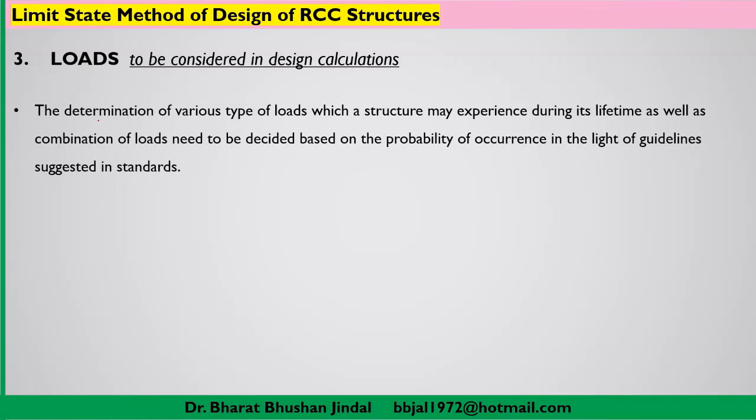Now, what are the loads which we are going to consider? First of all, the determination of various types of loads which a structure may experience during its lifetime, as well as the combination of loads which are required to be decided based on the probability of occurrence in the light of guidelines suggested in the standard.